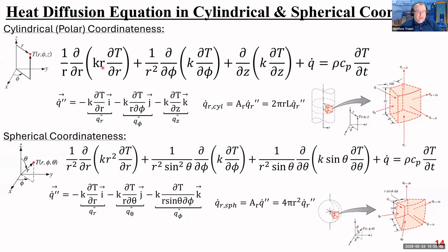In order to get the heat diffusion equation, we do the exact same thing that we did before. We take a representative slice of this thing. This time it's dr, dz, d theta, right? So those are the 3 spatial directions. And then we just look at the heat flux through the r direction, the z direction, the theta direction, and then add up all that heat flux, preserve the potential for an energy generation term, preserve the possibility for heat storage, right, and transient temperature changes in this object.